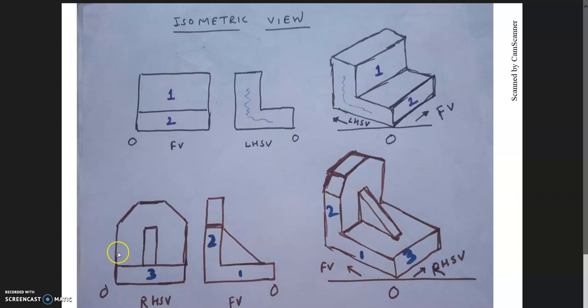While drawing the ribs, you can observe here, this is ribs. Okay, so looking from these sides, you can't see this inclination, but you can see only this length. So this vertical length is equal to this length. This is more important, and this thickness is equal to this thickness. So it is more important. So again remember that this is the basics of the isometric view.